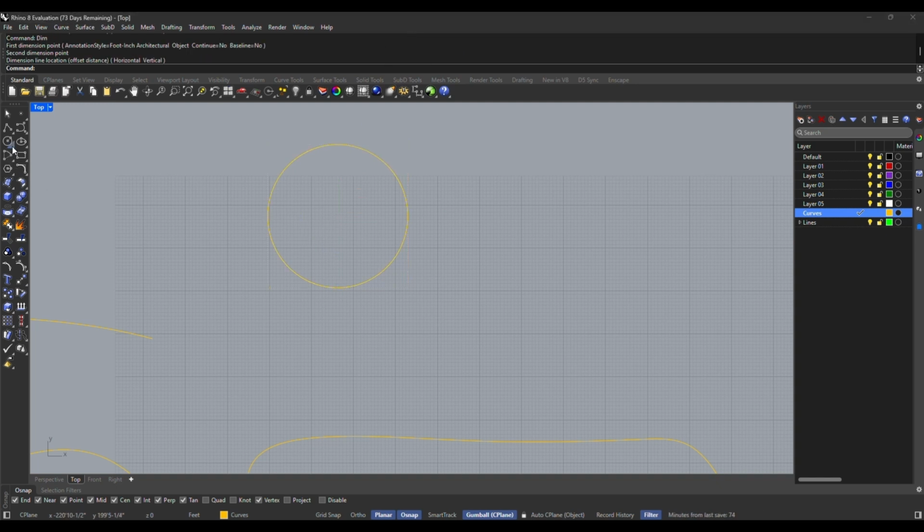And same, you can try another type of circle, and from here you can start from the end of the diameter. So start from here, and then you can give it the number or amount, for example I'm gonna say 40, and then hit enter, and you can hit enter to end this diameter as well.